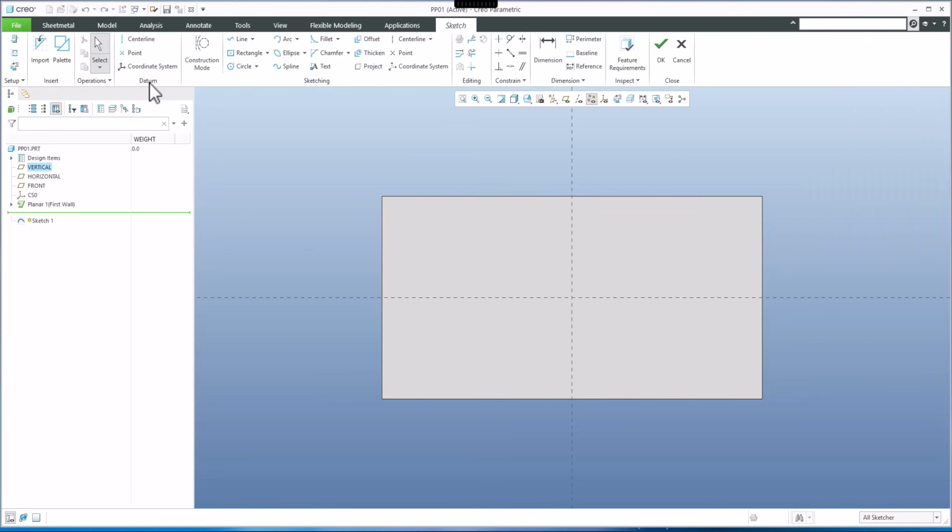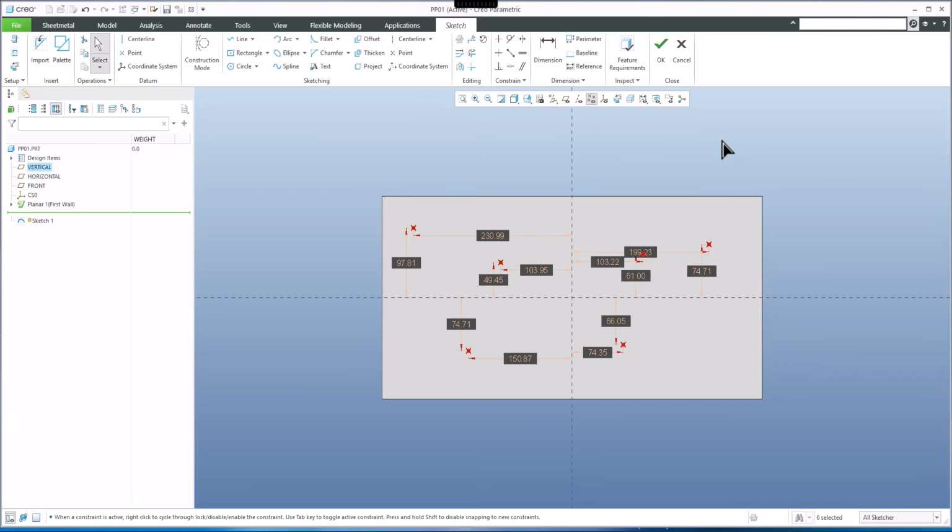And then we will create the points from the datum group. These points are datum points, so when we select it, we can apply the placement of the points. And when you hit the middle button, the system automatically makes the dimensions. You can create new custom dimensions, create a reference and so on. It's really easy to maintain these points. If I finish with OK,